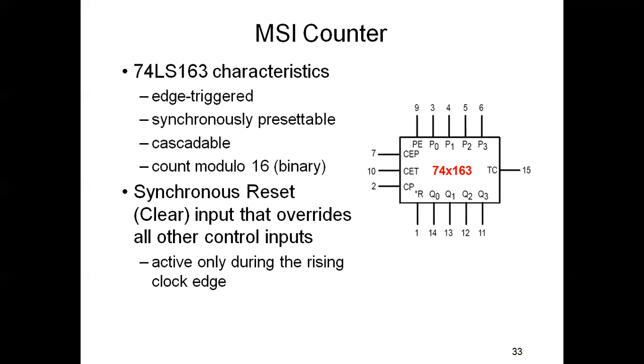It is edge triggered, synchronous, presettable, cascadable, and counts modulo 16 binary. The synchronous reset clear input overrides all the control inputs. It is the pin diagram in which we have already discussed all the pins: parallel input, parallel output, CET, CEP, CP, that is clock pulse. It is the block diagram of the pins.